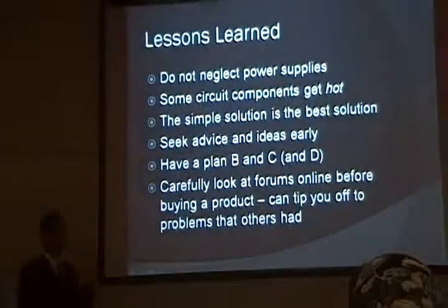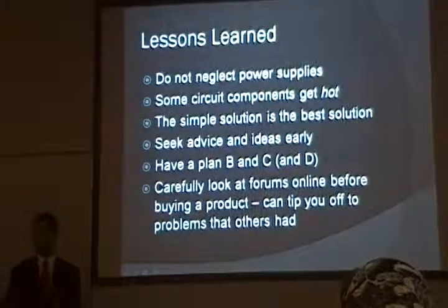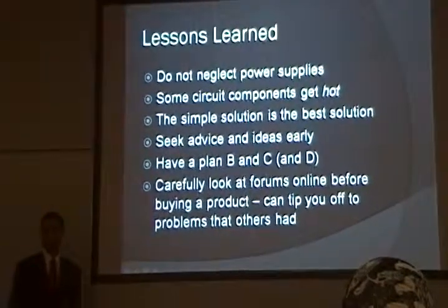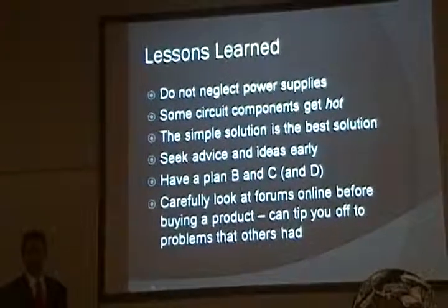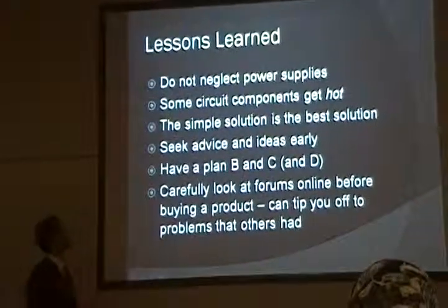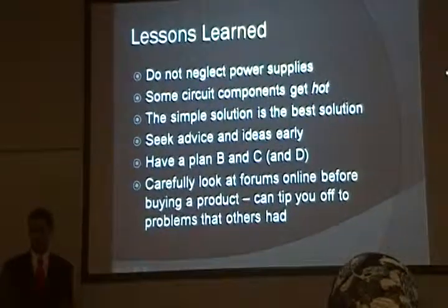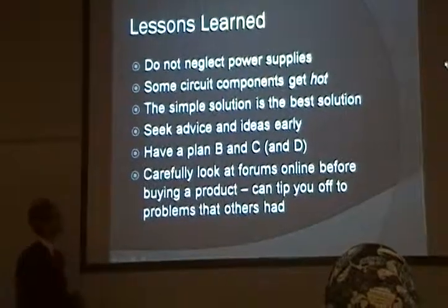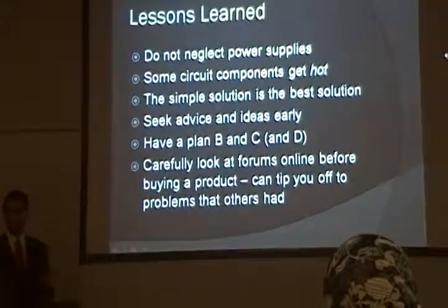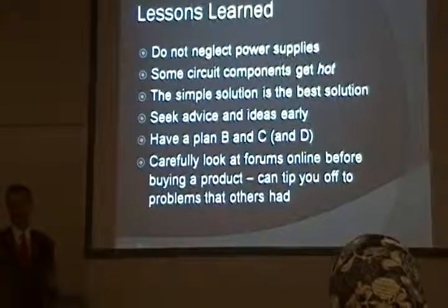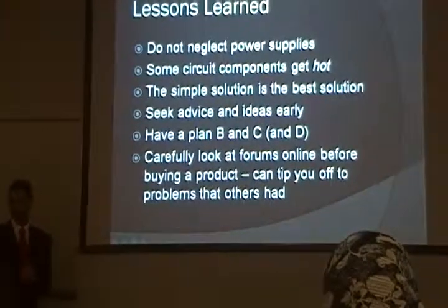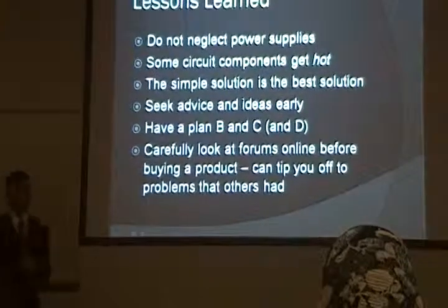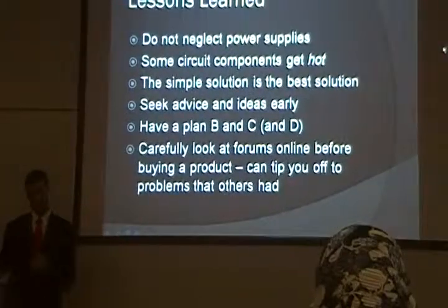Lessons learned. One of the most important lessons here, and if you guys are doing 492 now, do not neglect your power supply, especially on an embedded system. Power supply on an embedded system is never as good as a wall board. Some circuit components can get hot, especially voltage regulators. The simple solution is always the best solution. This was a very humbling realization for us. Seek advice and ideas from your faculty mentors and other faculty early. Have a plan B, C, and D.